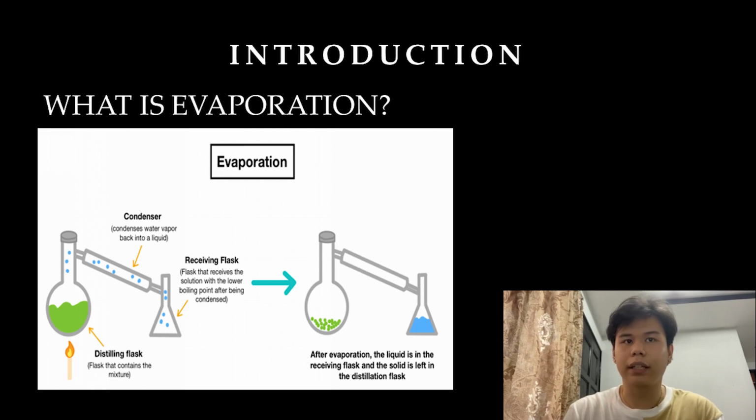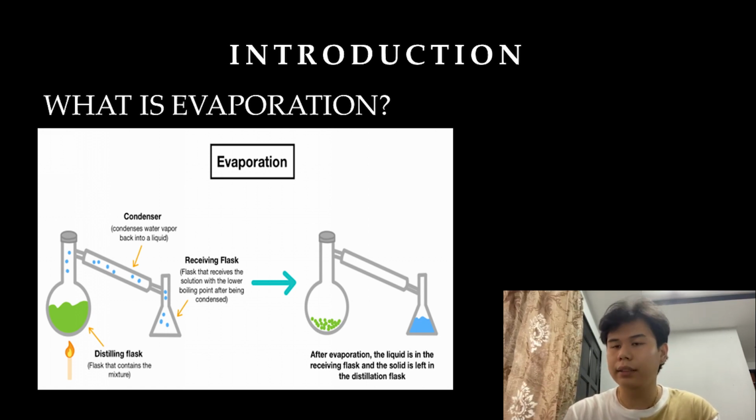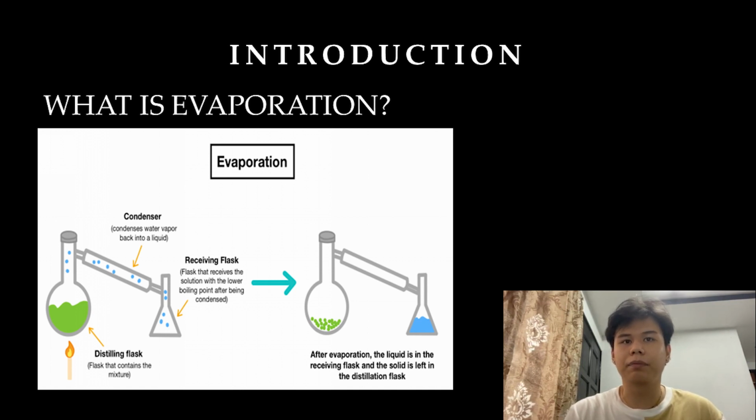Evaporation process is defined as one that starts with a liquid product and ends up with a more concentrated but still liquid and still pumpable concentrate as the main product from the process. In most cases, it is essential that the product be subject to minimal thermal degradation during the evaporation process, requiring that temperature and time exposure must be minimized. This and other requirements brought on by the physical characteristics of the processed product have resulted in the development of a large range of different evaporator types.